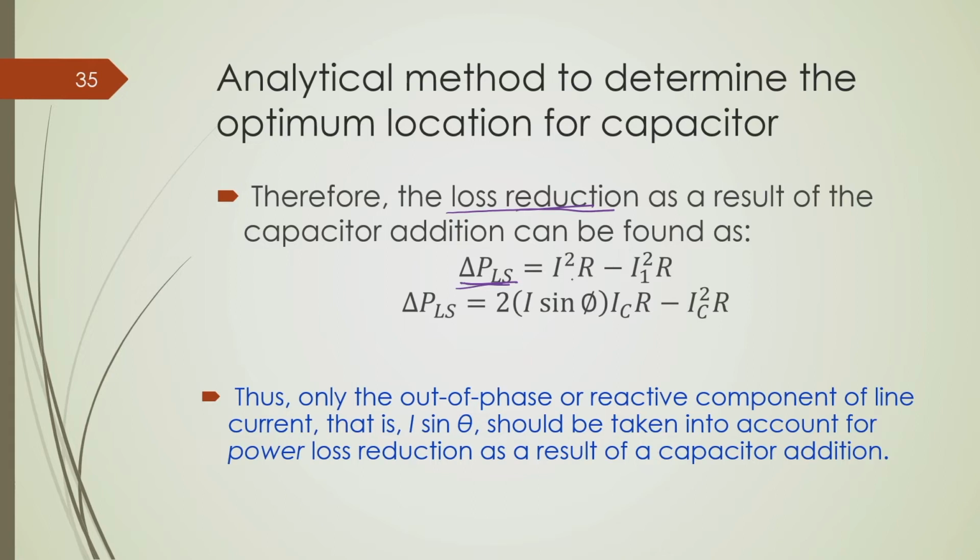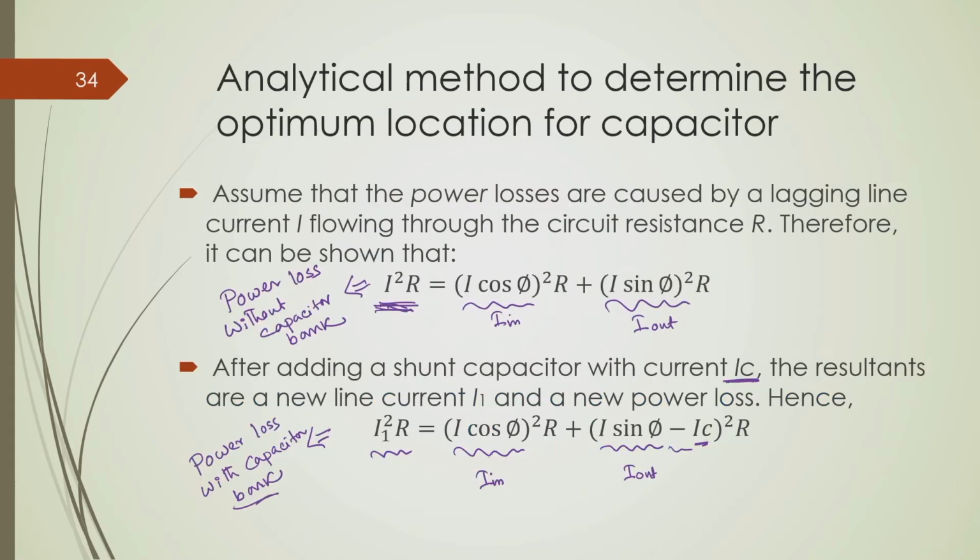If you take the difference of these two, then the in phase component of the power loss would be cancelled out, because there will be no improvement in the power loss which occurs due to the in phase component of the load current. Okay.